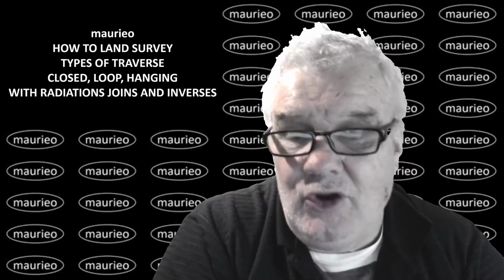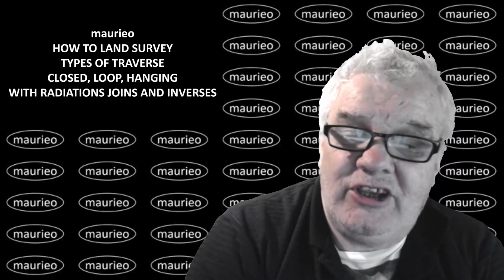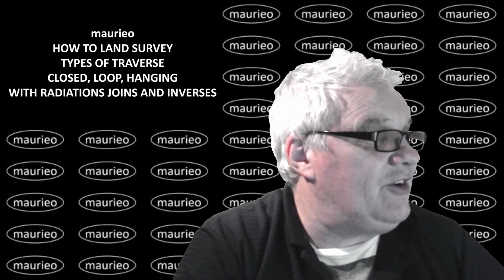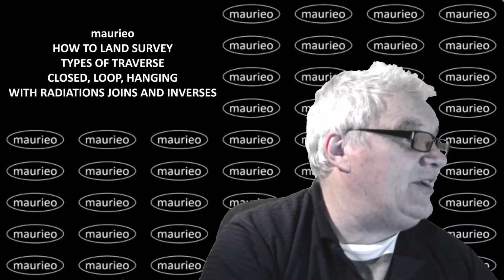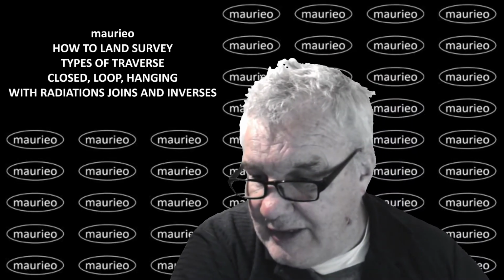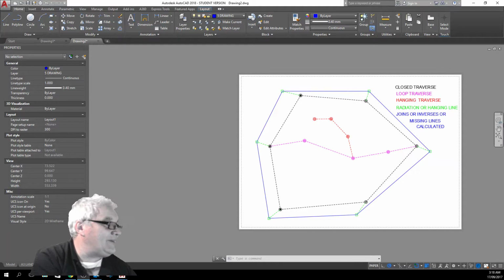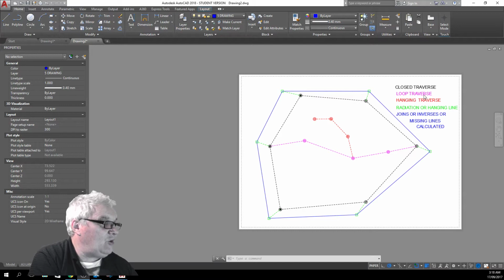Yeah, it's gone 27 minutes, so it's quite a lot. But hopefully you'll get an appreciation of the different types of traversing and the accuracy involved in each one. Now I'll just go back to the diagram. If you start there with the closed traverse, that's the most accurate. The loop traverse is sort of the next accurate. The hanging traverse, not quite so accurate. And the radiations or hanging lines, about the equivalent of the hanging traverse, same.